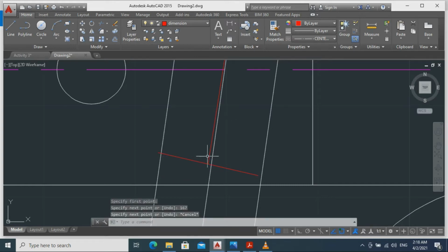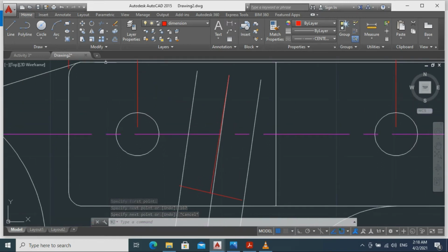Okay, then we're going to draw lines here by using our hidden line. So we're going to click that hidden to our properties. So upward, first let's change this to hidden. Okay, so we're going to set that to 0.88, tab, with an angle of 82 degrees. And we're going to extend this line to the left. Let's set that to 0.65, tab, with an angle of 173. Enter.